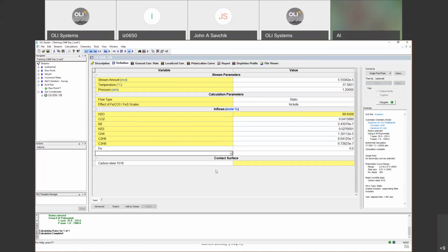So we will need to find interaction parameters, interactions of the metal surface with chlorides, hydrogen sulfide, CO2, the effect of pH, the effect of temperature, all of this information. And then we will regress the data and back calculate all of the information for you, and then we will add it to the data bank. If all the information is in the public data, then the alloy goes into our public database. If the information comes directly from your lab and is specific to you, then it becomes a private data bank that we provide only to you.